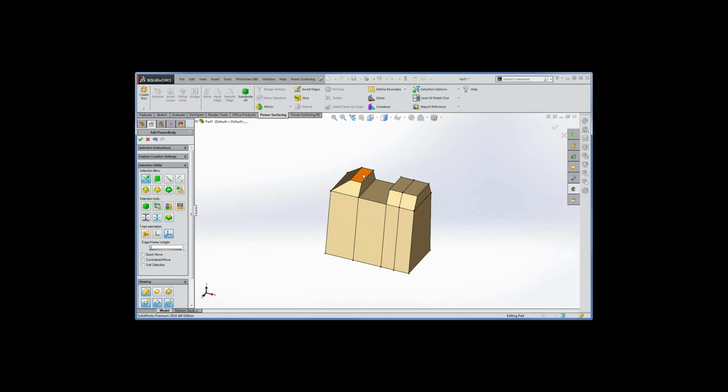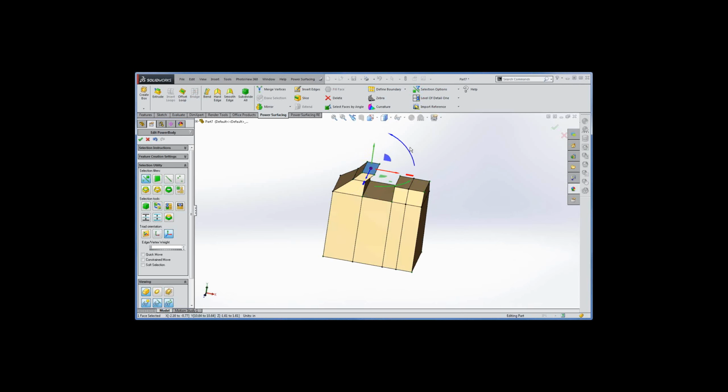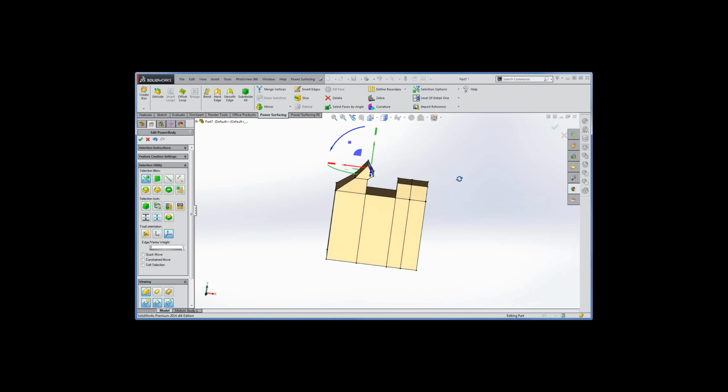And then I'm going to go over and once again hold my A key to extrude, and I pull this guy out, and then I'm going to rotate him into position. It is really a little bit too thick. Now, right now we're in world coordinate system, and it would make a lot more sense to scale it using local, and I can do that over in the left-hand panel. So I switch to local coordinate system. Now I've got my scale, and I can continue to move it.